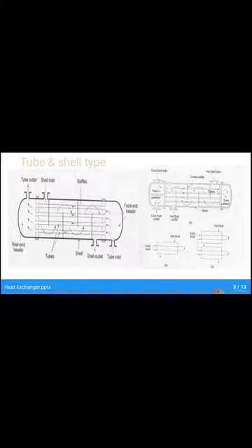While flowing, the hot and cold fluids exchange heat between them, and that is how we get the heat transfer. Also, to increase the efficiency, we provide a partition inside the container, as you can see in the figure. Due to that, the fluid from the shell inlet flows downward, then upward, then downward, then upward, and then goes out by the shell outlet. In the figure it is exactly shown.